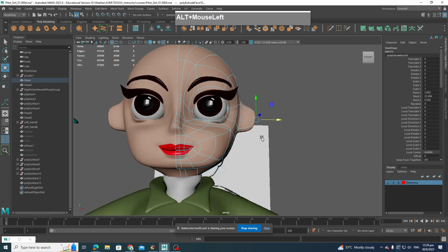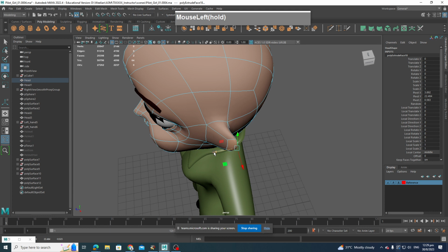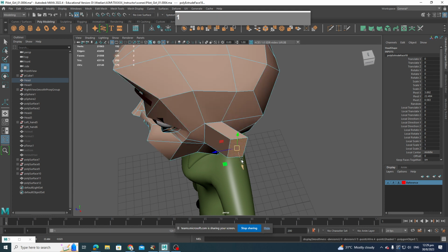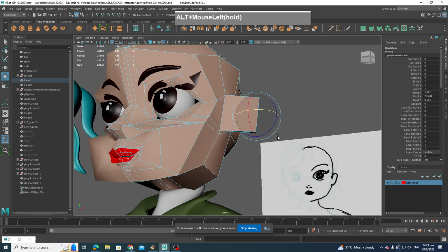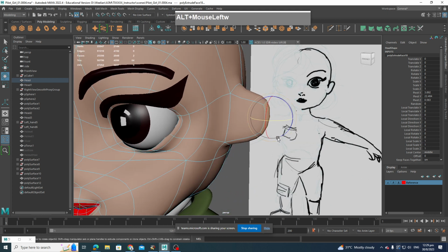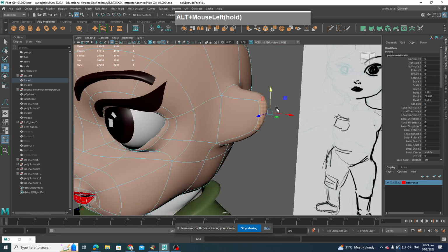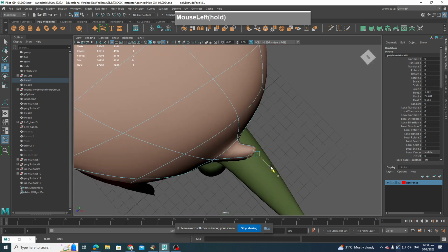Now the ear is not like Mickey Mouse like that. It needs to go back a little bit. And if you go to level 1, you can use the rotation tool to just rotate it like this. Right, then in level 3, we want to shift this face up a little bit so that it looks like the ear, and we can push this thing back in a little bit.